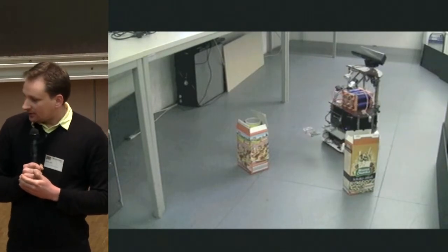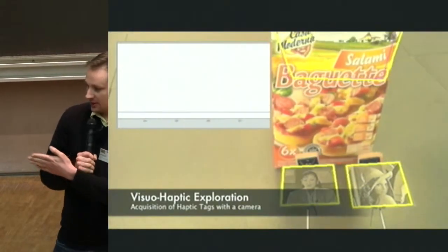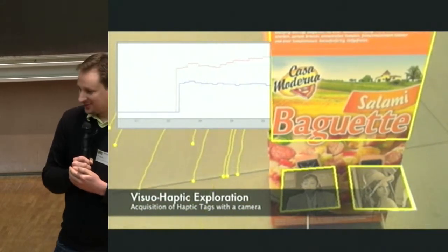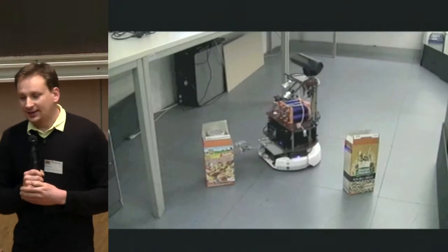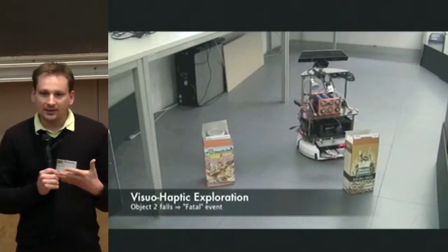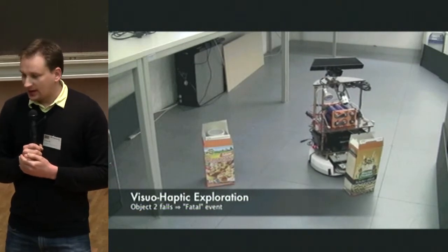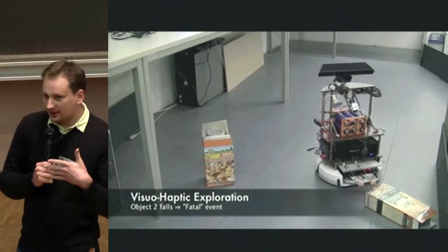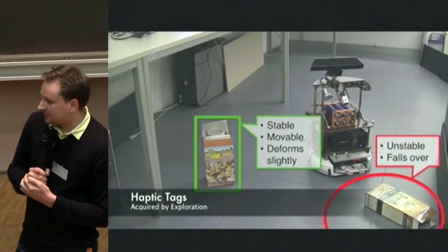And you see now that the camera tracks both the sensor, that's the template on the bottom, and the object itself, and measures the pushing force and measures how the floor moves. And as all of these data come from a single video frame, we know that our measurements are naturally coherent, and we do not have to synchronize any external haptic sensor with vision.